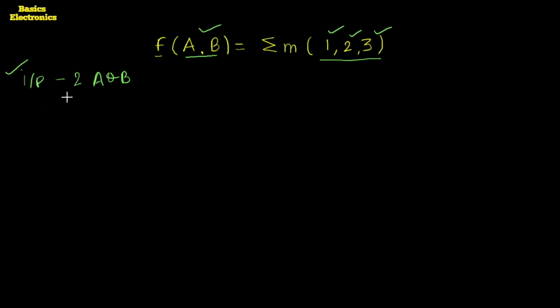Now the second step is to decide the multiplexer. These input variables are nothing but the select lines of the multiplexer. So we require a multiplexer having 2 select lines, which we can use for the implementation of the given logical expression. The multiplexer we are going to use is the 4 line to 1 line multiplexer, because the 4:1 multiplexer has 2 select lines.